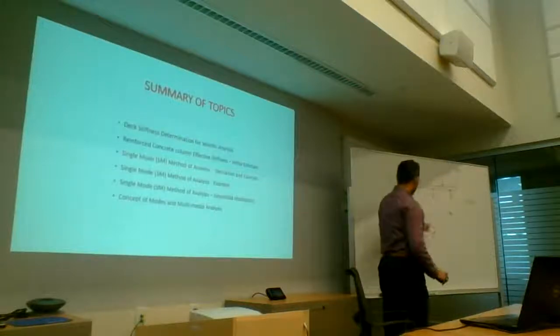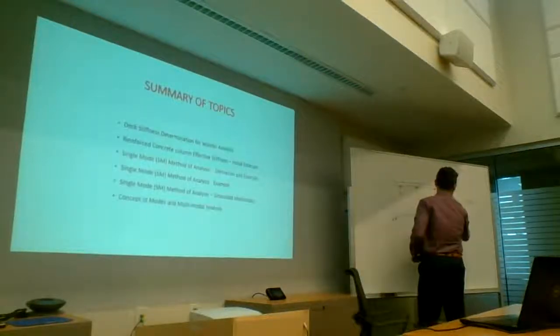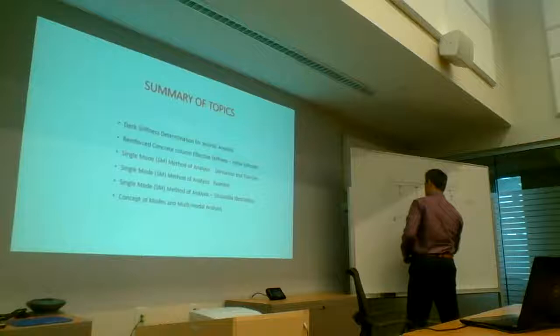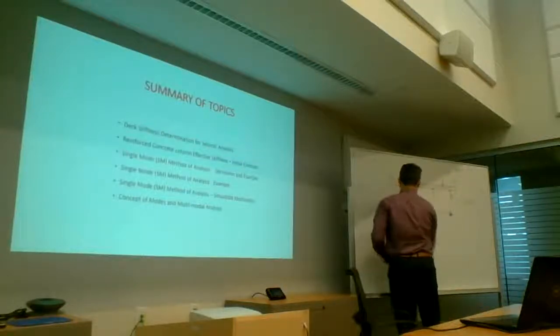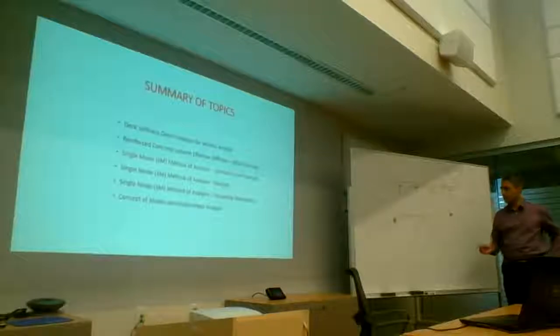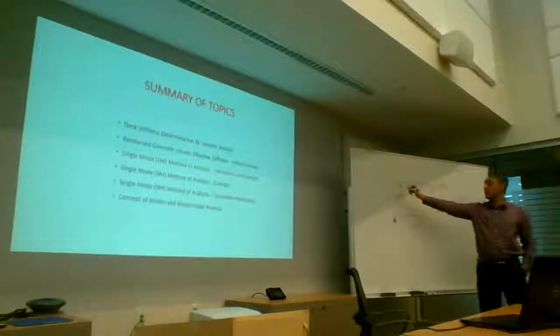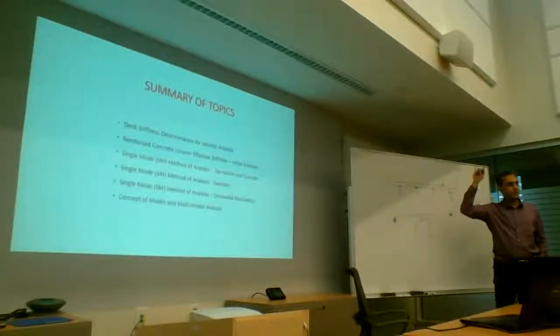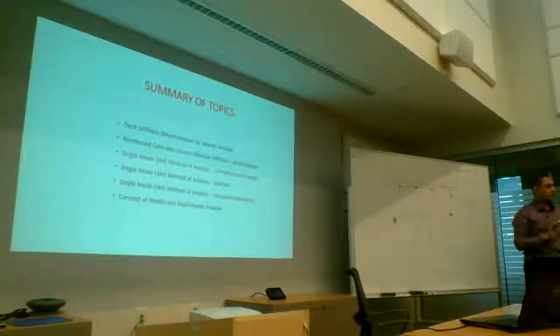Okay, so you can model the one bent, and let's say that longitudinally your abutment is free. You should really just be working with beam elements. There is no need to have this as shell elements and brick elements and all that. That's not the intent, right?